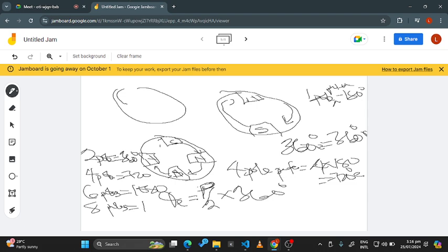So this is the relation, or you can write it as the total electrical degrees is equal to the total number of poles divided by two, or the pole pairs, which is small p, times 360 degrees. I hope this makes sense. Okay, now look at something else.